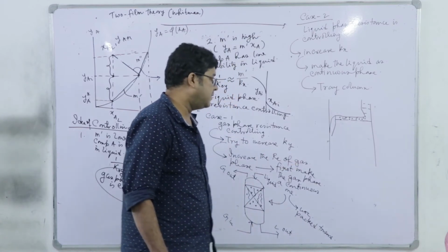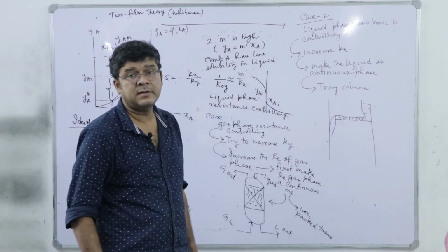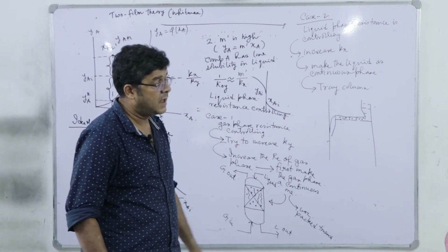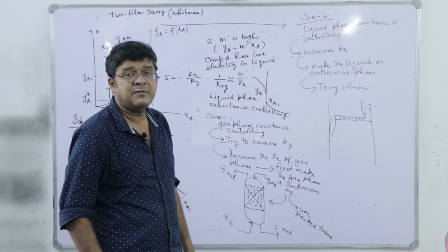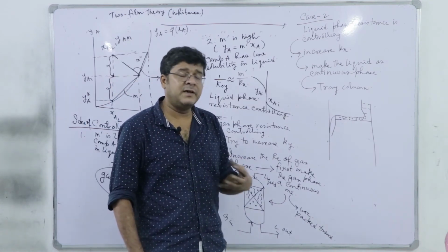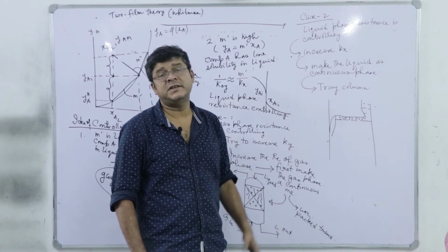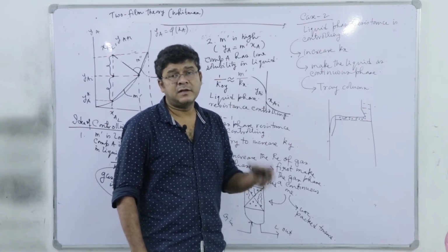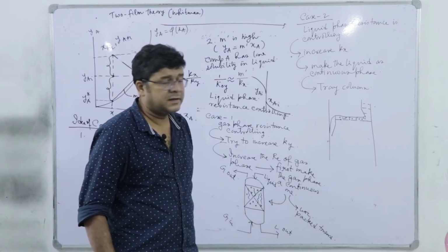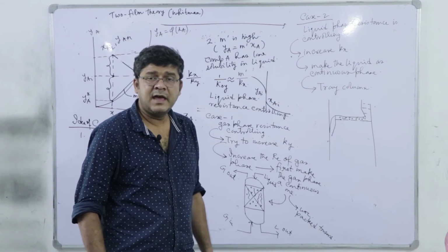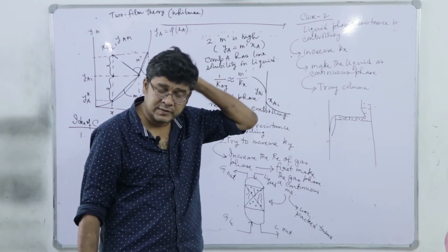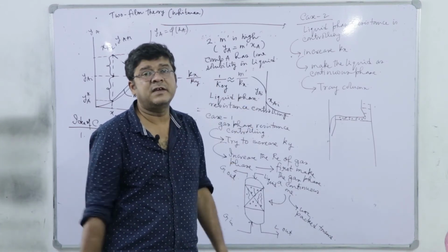And that is the reason, you see, in distillation and in different absorptions also, where we are using a solvent, though definitely it is a rare case, in which the solute has a low solubility, right? If the solute has a low solubility, then the liquid phase will be the controlling resistance, and mostly in distillation, the liquid phase resistance is controlling, we will discuss it later.